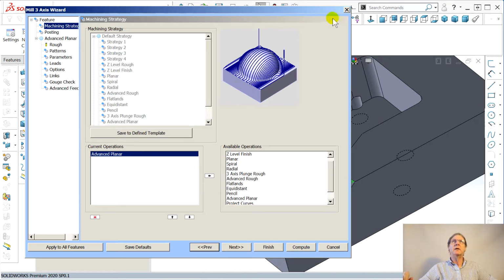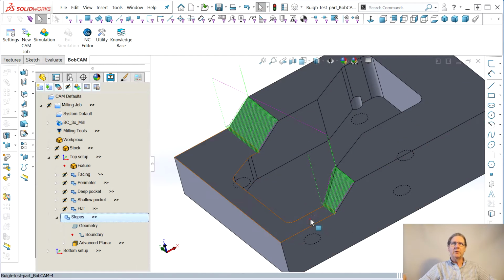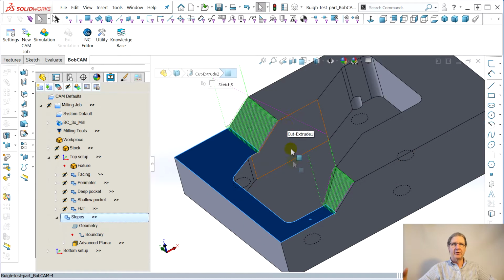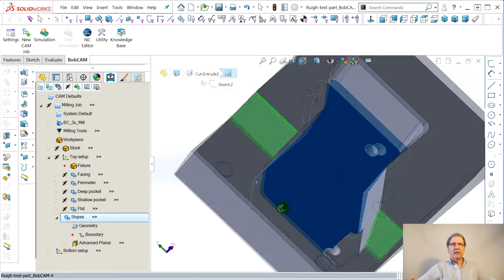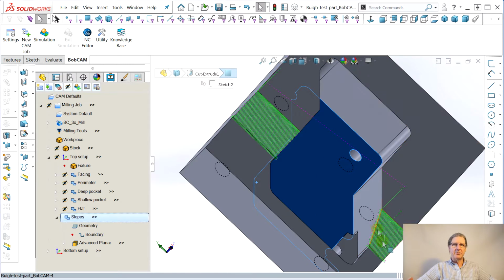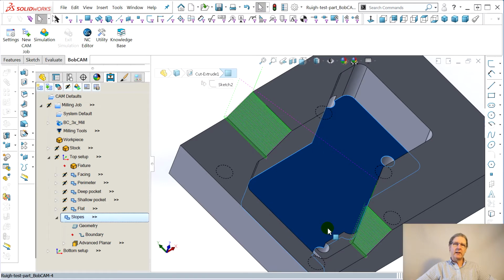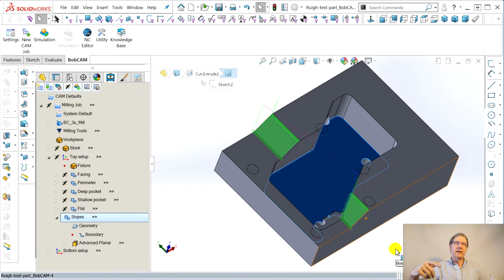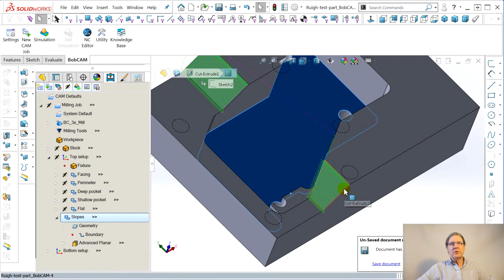Here, let me show you. There were 3 problems, okay? The gouge is the third. The second problem was it would leave material along this angle. All the programs have been doing that. Something to do with the math about this not being a rectangular patch. It's a trapezoid. So the tool pulls up a little. I fixed that with 3D extents on that Z level one too. So it goes a little further